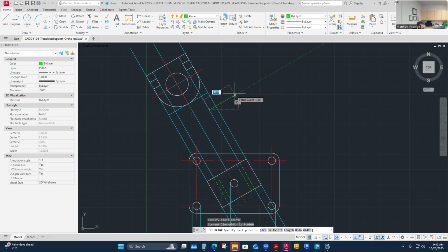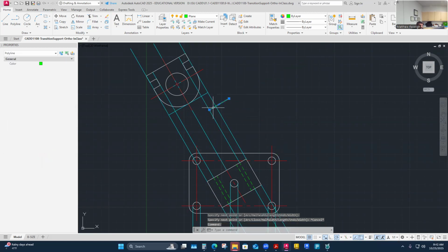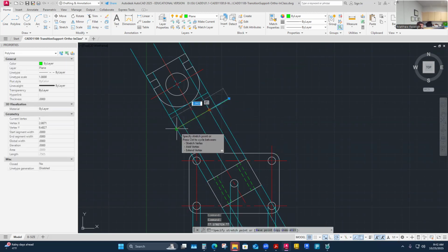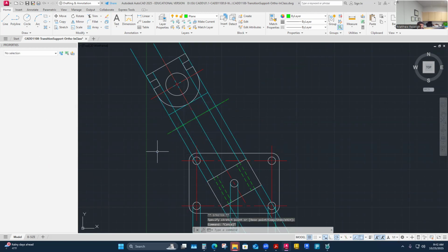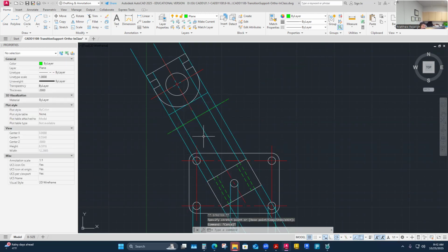Technically, this doesn't have to be any more than what I'm looking at, and I'm only looking at a partial auxiliary view. So as long as my viewing plane is wider than the extents of this part that I've drawn in my auxiliary view, that's sufficient to grab the view. I don't necessarily need to come clear out here unless I was doing the full auxiliary view. So I'm thinking of at least pulling it beyond that mark a little bit, this mark here. Oh yeah, like here. And then I might extend this way and beyond a little bit. No specific length, but this is a viewing plane looking that way.